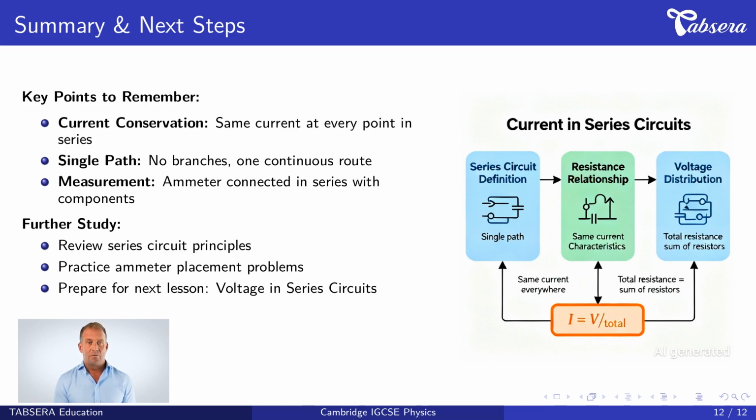Third, measurement requires connecting the ammeter in series with other components. This allows the ammeter to measure actual current flow without creating alternative paths. For further study, review series circuit principles regularly, practice ammeter placement problems to build confidence, and prepare for the next lesson on voltage in series circuits, which builds on today's current concepts by exploring how voltage divides across series components.